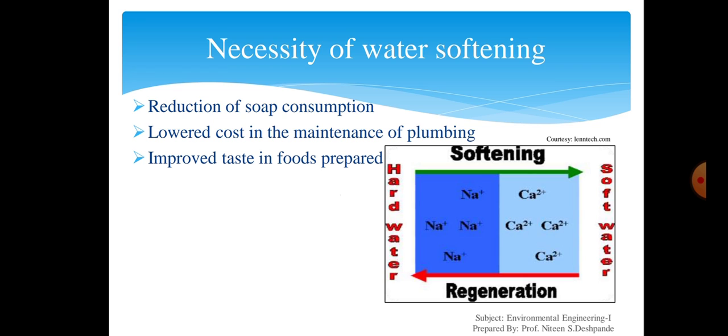We know that hardness can cause rusting or corrosion of the pipes, which is not good as far as the service life of the plumbing pipes is concerned. Also, softening reduces soap consumption, and if we soften the water it will improve the taste of the food which is prepared.